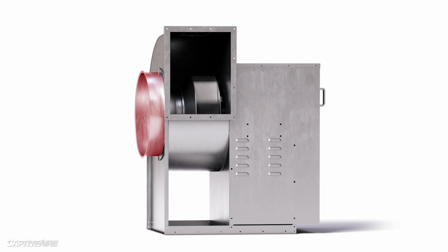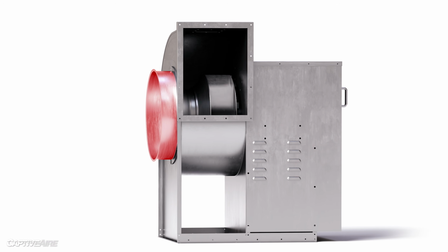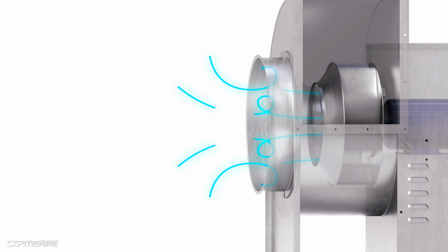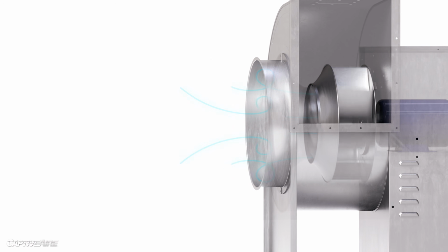Let's take a centrifugal fan in free air. System effect is typically most apparent on the inlet side. So we'll first study what's going on here without any ductwork attached. The air that's drawn towards the fan here comes from all directions around the duct. And since it enters the inlet plenum and wheel right away, there's not enough room or time for all these airflows to even out, and a lot of turbulence and swirl are happening in this area.